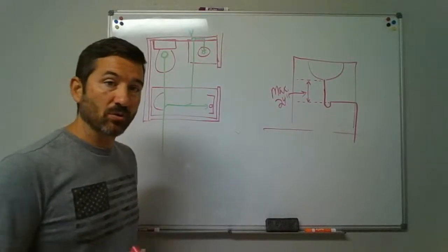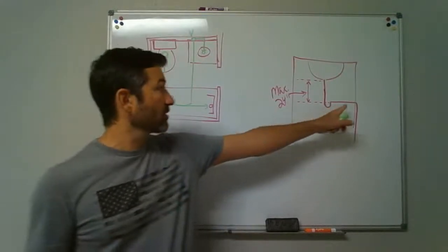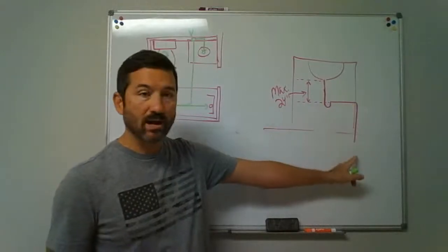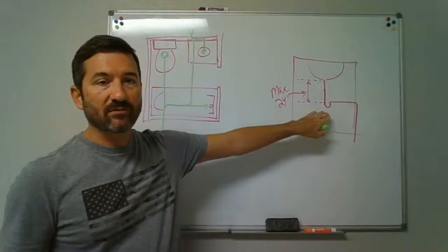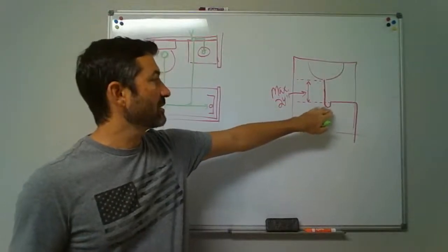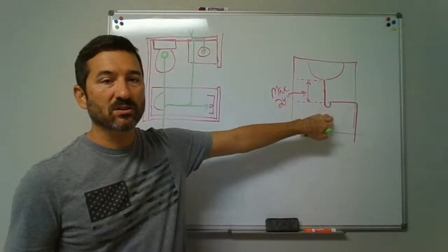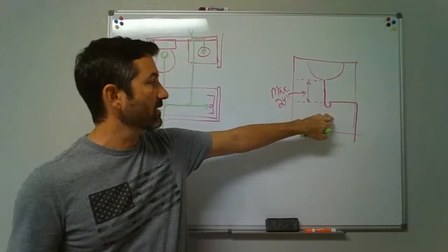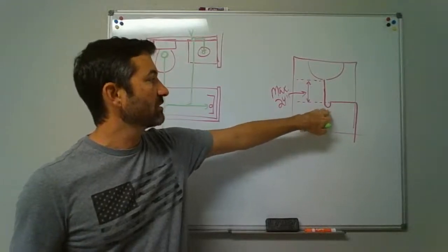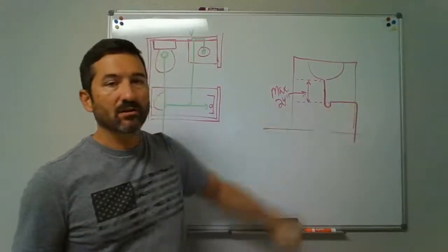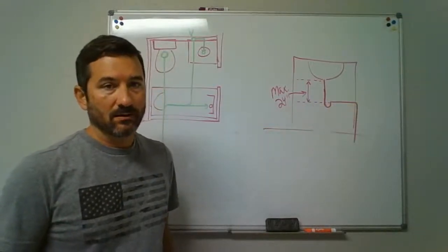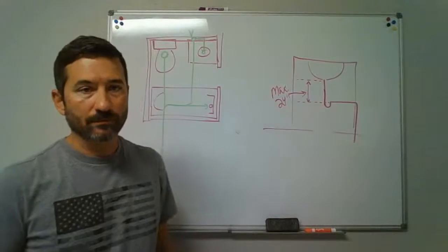So we couldn't drop more than 1.25 inches. Surely going 1.25 inches, I can't go down and get below the floor. Let's just say I went up to 1.5 inches because that's what I normally plumb them at. That's not the minimum code. So on the state exam, I'd want to say 1.25 inches, but most of the time in the field, I put 1.5 inches on these. Then the maximum drop I can have is 1.5 inches. Still not going to get me below the floor.